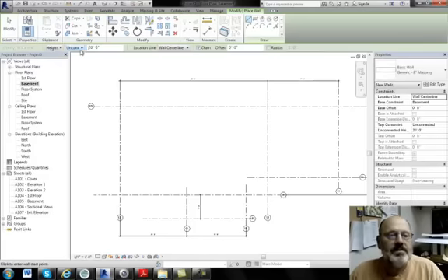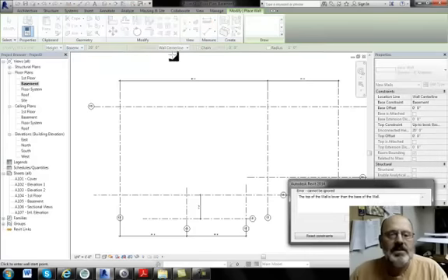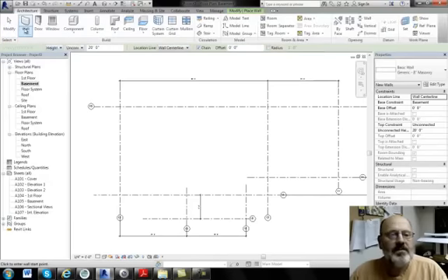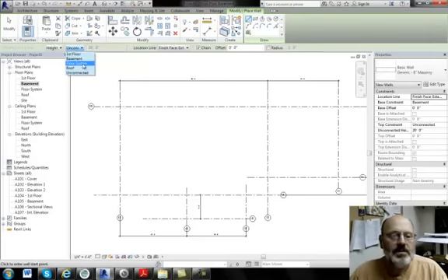So height, don't need to do that. Constrain to the basement. It's lower than the base of the walls. And they're going to be finish face exterior. Basement, I'm going to constrain them to the floor system from the basement. I'm sorry, I set that wrong. So here's the base constraint as the basement. It's going to go up to level floor system. So I was lying when I said basement here.